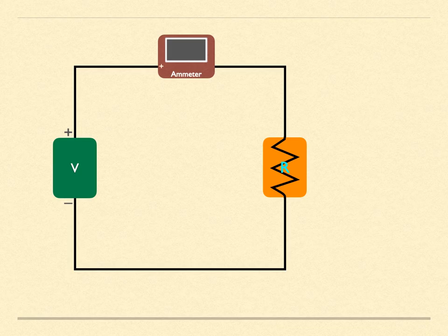Connect the positive terminal of the ammeter to the positive side of the circuit. Connect the negative terminal to the negative side of the circuit. The positive terminal is commonly colored red. The negative terminal is commonly colored black. In addition, it's sometimes labeled as common or just COM or even ground. And you do have to break a circuit in order to insert an ammeter. But once installed, you can then turn on the circuit. If the measured current is negative, you have connected the circuit incorrectly.